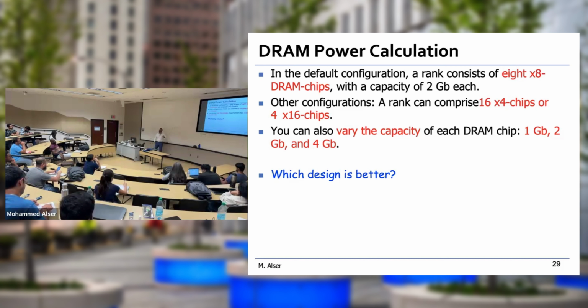This is really kind of a debate. Which one is better? To have a chip in the DIMM module giving you 8 bits or 4 bits or 16 bits. Now remember, we need 64 bits all the time. So if we have 8, that's going to dictate the number of chips. So we need 8 of them. If we have 4, we need 16 of them.